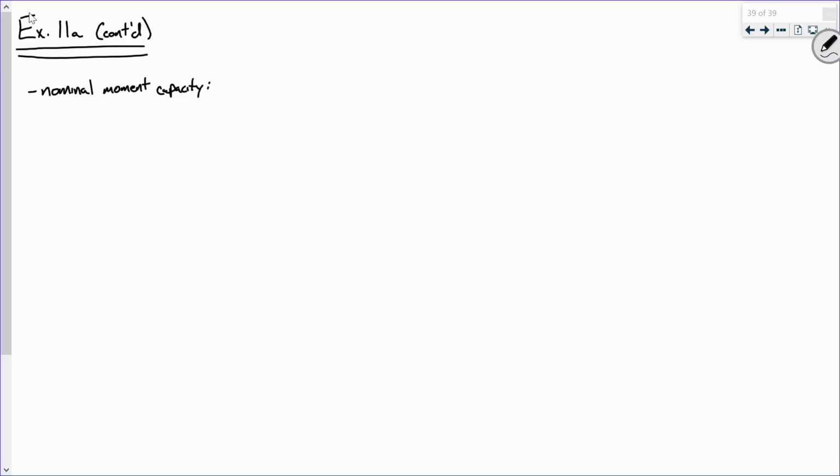We have C sub C, which is 0.85 fc prime a b. So we have 0.85, fc prime is 3 ksi, what was a? There we go. And b is 14 inches. Plug and chug and tell me what you get. 255?